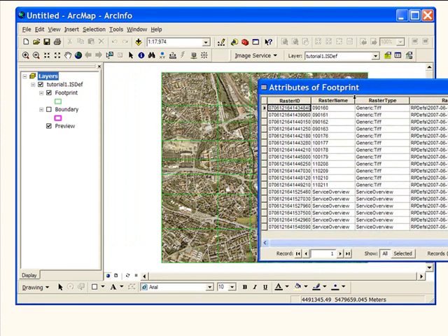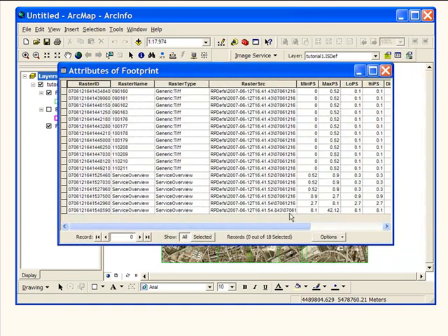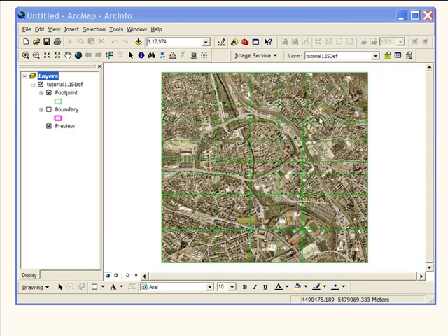The service table acts as a catalog of the raster datasets that make up the image service. You can look at each individual image file and see what their footprint is within the entire set. Notice how the images overlap. Select the Image Service Overview and you see that it covers the entire area. The information in this table is used to decide which imagery should be used when creating a mosaic at different pixel scales.